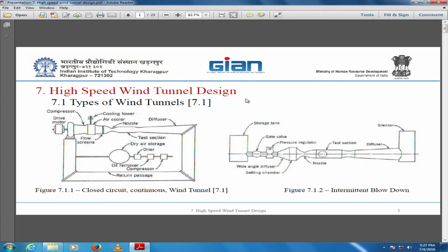For supersonic conditions, sir, it is a convergent duct that acts as a diffuser. But here I see only a divergent duct acting as a diffuser. No, you see, after the nozzle there is a converging duct. The second throat is there. Nozzle is here, and behind it you have a second throat. That is a converging.